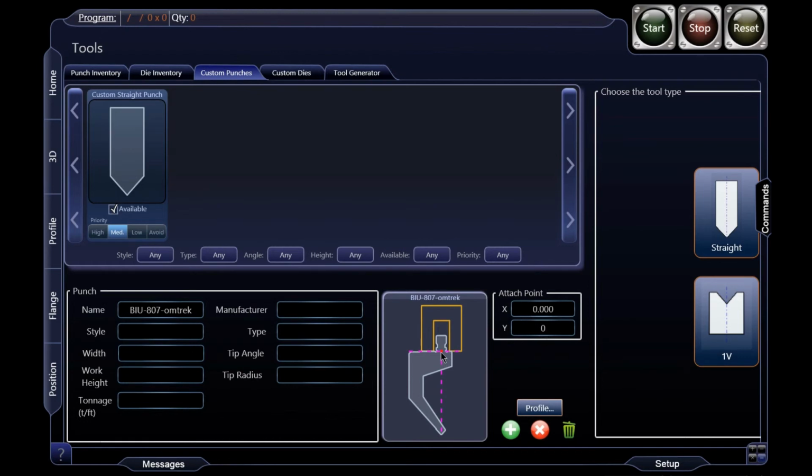If you don't have your origin in the right place, say if it's way over here or way over here, if you don't know these numbers, it's very hard to guesstimate. You'll be picking and choosing, and you're likely to make a mistake or have the wrong number in. So that's why we put the origin there. Makes this real simple. Bring it in at 0, 0, and it lines up perfectly.